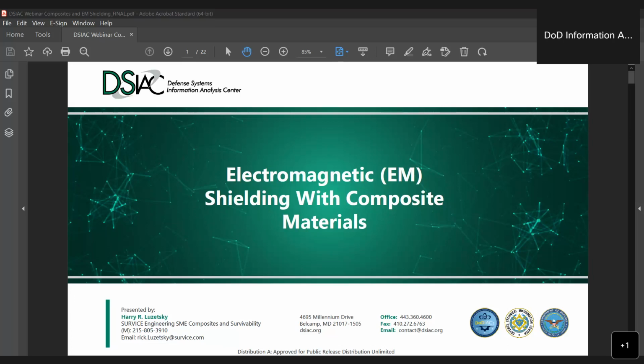We got questions about the copper mesh layers. Two questions asking about the grounding. Are those copper mesh layers grounded or are they floating? They are floating within the material. What happens is they are placed in without any additional resin system. So the way we are looking at it is you have the intimate contact between it and the graphite. While they're not grounded, there is some connection between all the different layers, but they are free floating within the composite.